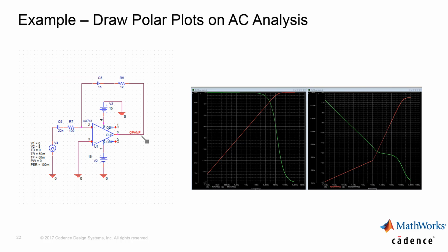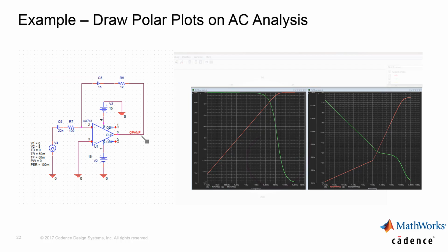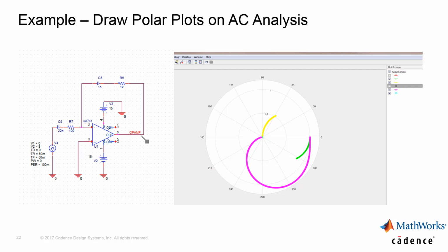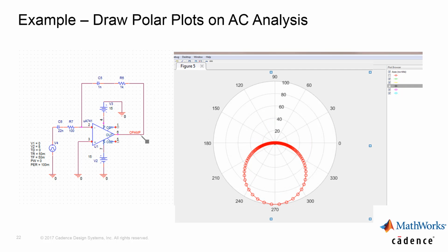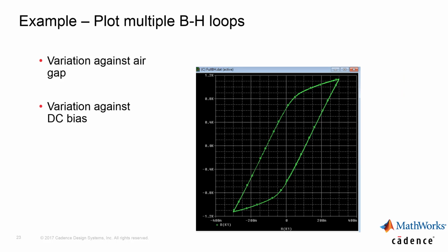So if you're running an AC analysis in PSpice, you can view the same results in MATLAB as a polar plot. Here's another example. So you can take any of those data of transient or AC analysis into MATLAB and view it in a different format.